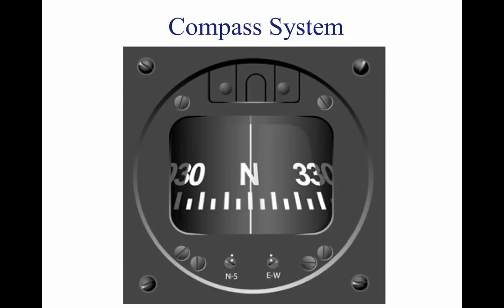When the pilot is flying north, as the compass shows, east is to the pilot's right. On the card, 33, which represents 330 degrees west of north, is to the right of north. The reason for this apparent backward graduation is that the card remains stationary, and the compass housing and the pilot turn around it, always viewing the card from its backside.